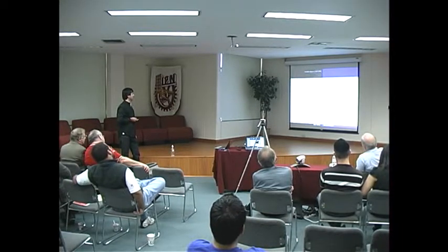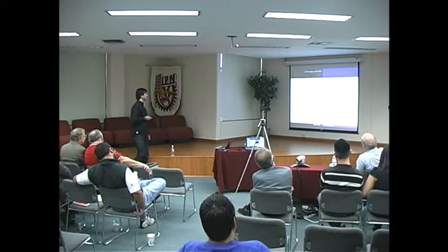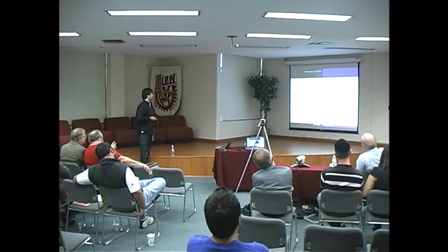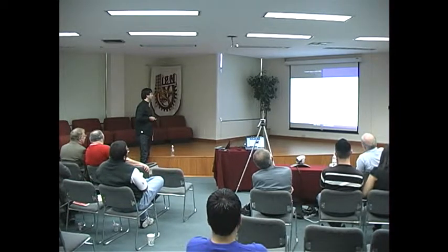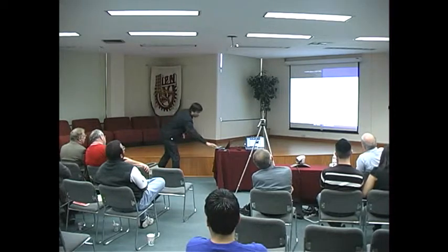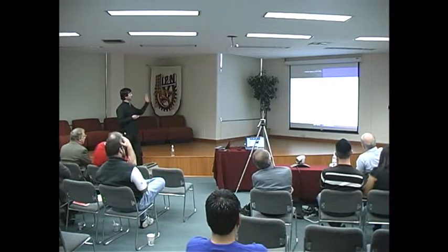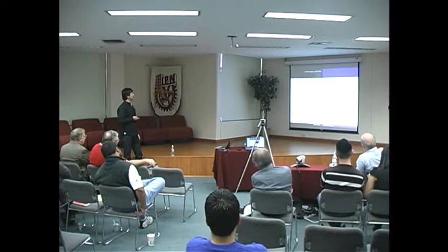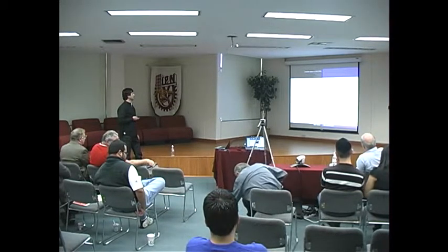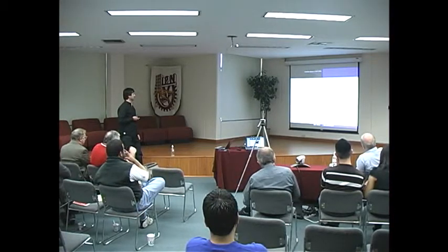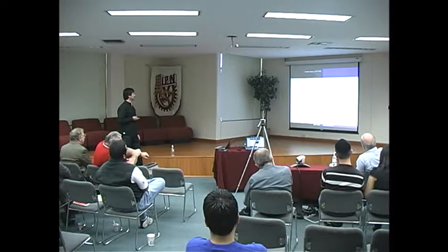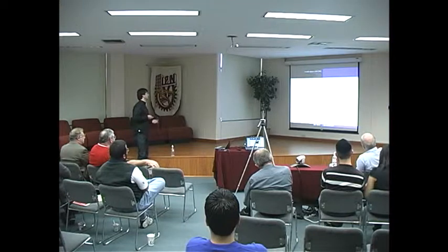So by defining these errors, which are the difference between the inductor current and the desired inductor current, and the difference between the output voltage and the desired output voltage, we computed the dynamics of the electrical part, which is given in two parts. Here we have a linear part, a very nice linear part, which, if we neglect these two terms, is exponentially stable. And this part is introduced by the observation error and the saturation function.